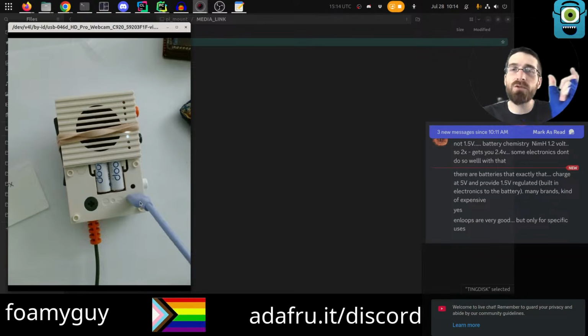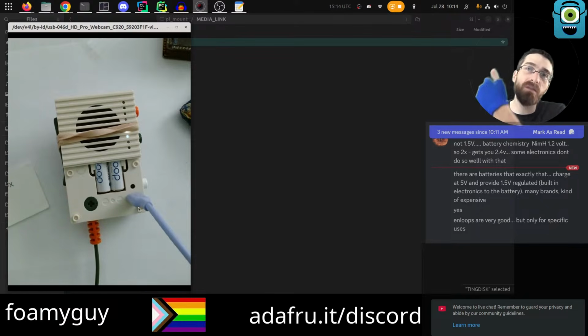So then I have 2 USB things. If I plug them both into the same computer, I get a weird feedback sound in the audio recording. But if I split them, so this is plugged into the Pi over there, and this is plugged into the computer I'm actually on here, then that's gone. So I was thinking the batteries would help solve that too, because power would not have to come from USB.